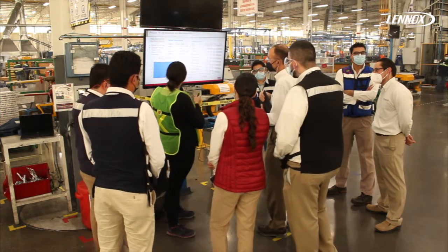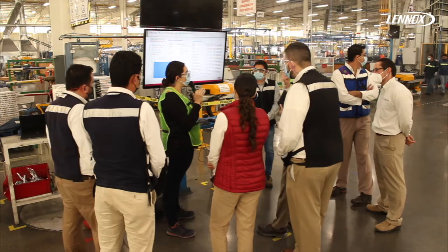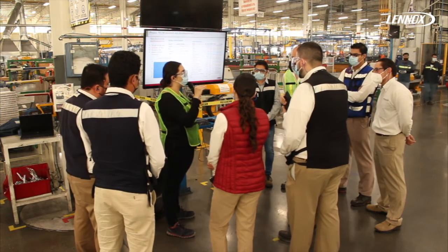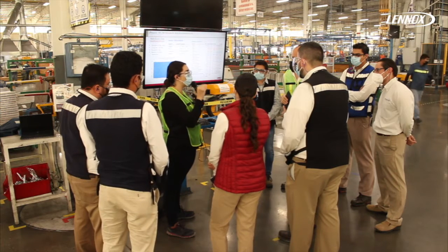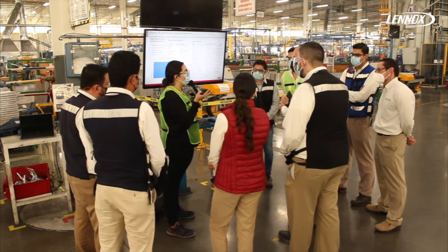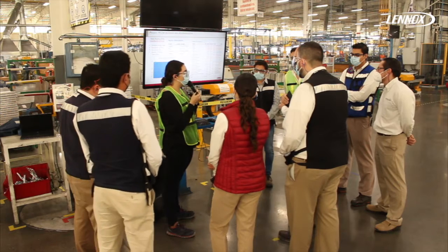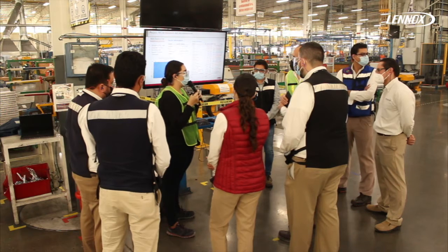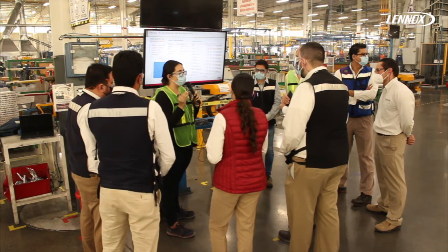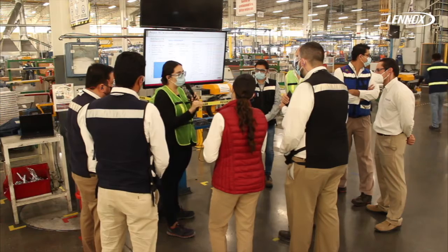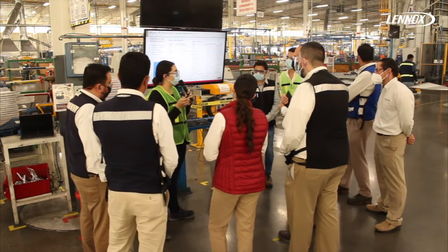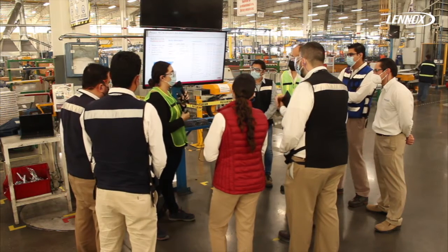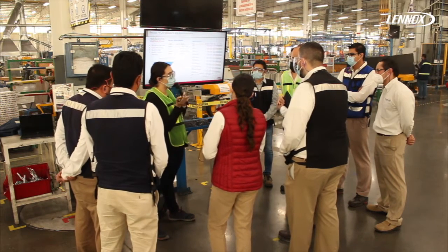Well, for example, for the height of the slab, we are now measuring. We implemented a sensor that will tell us where the torch is going to point in our slab. In that way, we can improve the process. For the quantity of flux, we're going to be measuring. We are going to make sure that every one of the rings is completely full, and we're trying to find a way to make it automatic and not only measure each of the rings, because there are a lot.